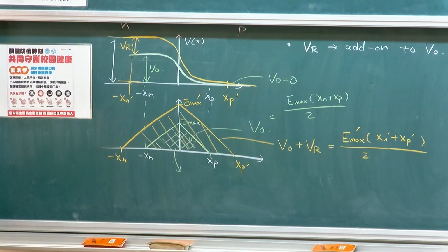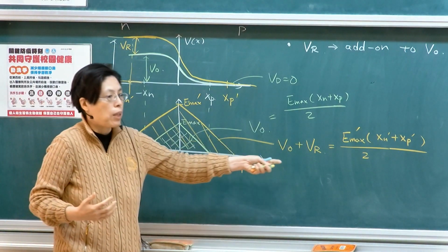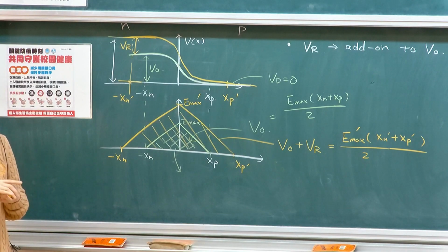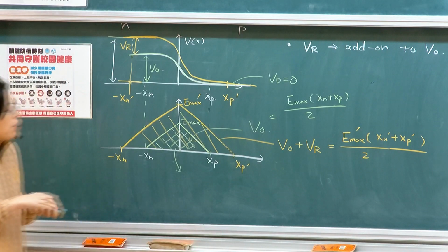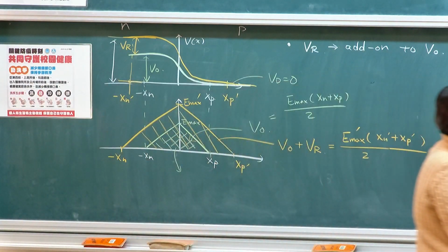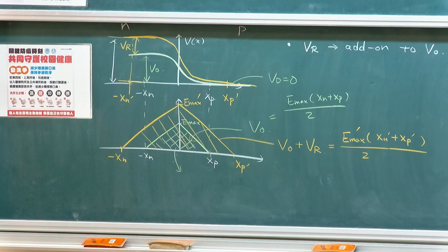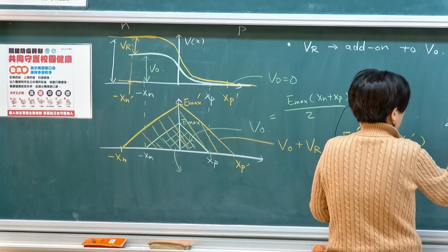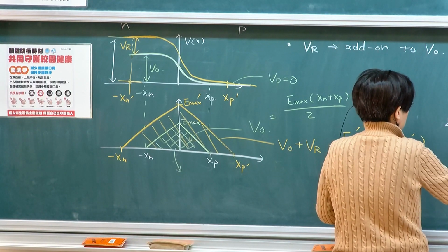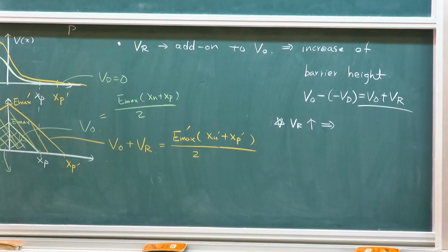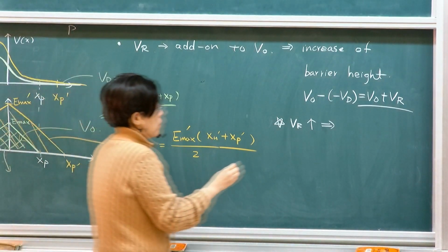Okay, so how much you grow the triangle corresponds to the voltage being applied, the voltage being sustained on this junction. So this is what happens in the reverse bias condition. If you think about it, when you're applying a VR and you increase it, you're actually creating a higher electric field.